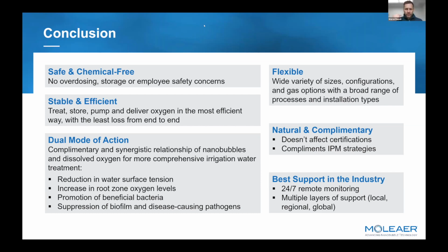And I think just because I see it here, Michael, and I'll touch on it, Gez is asking how do we, because it's related, we produce our nanobubbles through a hydrodynamic diffusion process. And again, the reason why we have adopted that is because of this limitation of head loss through a system. So when you're looking at the irrigation system, as I said, we've got this evolution of treating the water at source, and then ultimately the degrees of treatment when you go further and further into your irrigation or the field, you have accumulative head losses that are potentially there.